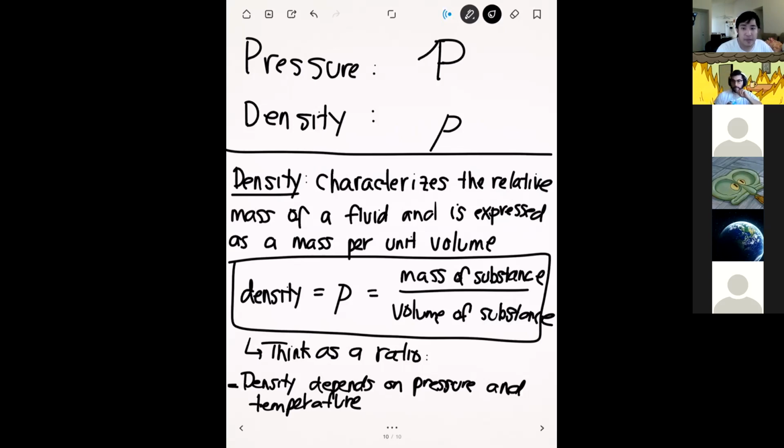Okay? All right, so the question is, is there a relationship between density and viscosity? Generally not. You'll see fluids with really high density and low viscosity, and you'll see fluids with high viscosity and low density. A lot of that depends on the chemistry and the molecular interactions in the fluid. There are fluids all over the spectrum, so generally there's no relationship between the two.